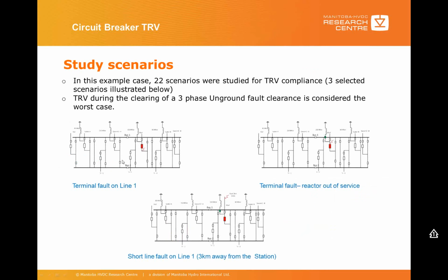These are a few study scenarios you have to consider, some examples. When you're studying, maybe you're applying a terminal fault. Maybe you have a reactor close by, with the reactor and without the reactor, and maybe you want to study a short line fault. These are some scenarios down the road we have to consider during your study.